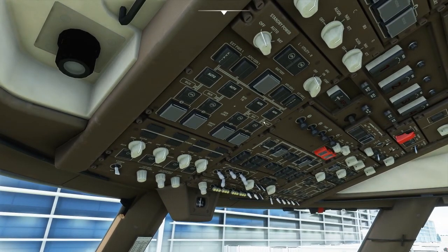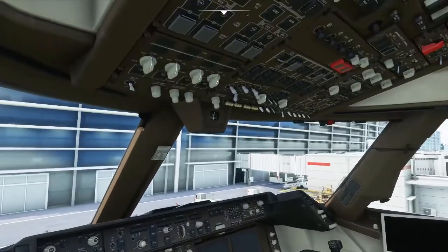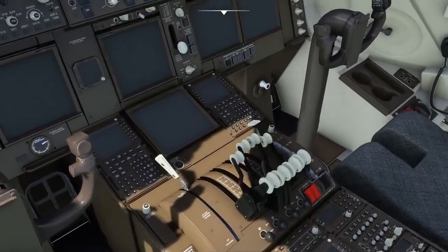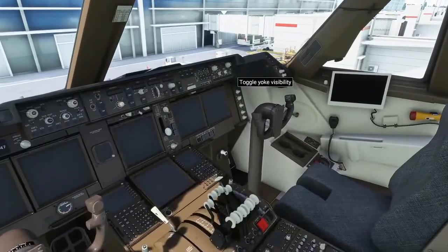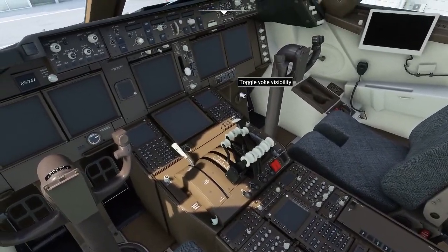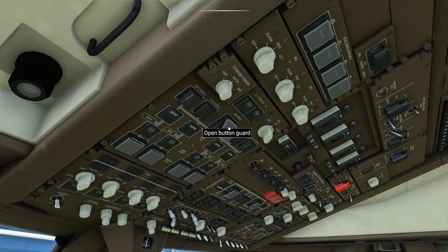So one of the first things on it is to basically make sure of a couple of things. So that standby power should be in auto, and that's one of them. There were other things on it as well, like make sure the flap lever is up. It was basically a few things just to make sure that whenever you turn the battery on, nothing strange is going to happen that you're not expecting. So flick the battery on.